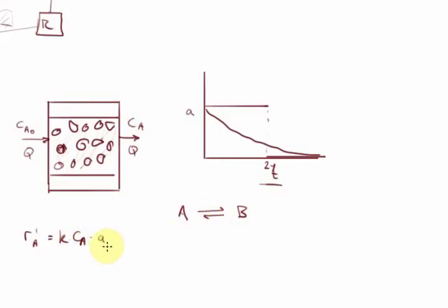And so initially A equals 1, and so we have a nice high reaction rate. And then as time goes on, A becomes less than 1, and it starts tending to 0. So as A drops, then the observed reaction rate drops. And of course, we don't want this to happen. We want to change the temperature in here. And if we do that, then we are going to increase this reaction rate. So k will increase. So we want to choose temperatures such that we achieve that nice high initial reaction rate.